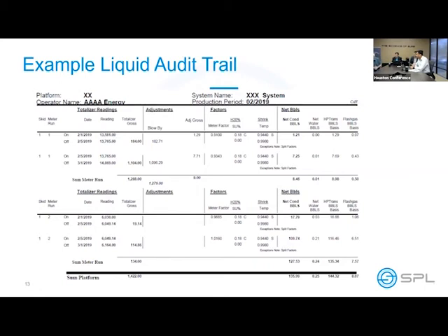Normally, when we get into onshore systems, this is where we're depending on oil compositions, because a lot of times in the onshore arena we're flowing that oil through stabilizer towers, heater treaters, stuff of that nature. So we have to simulate what that looks like. It's really hard to simulate that in the actual laboratory or in a physical shrinkage type situation. So that's when we're using process simulation models. For the most part, in the onshore environment, we're depending on those oil analyses. Yes.